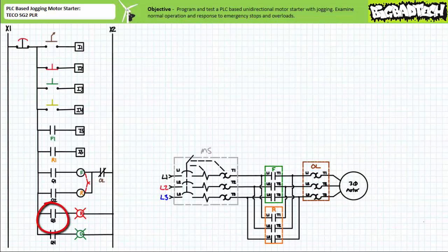Electromechanical relay output Q3 directs the operation of a red pilot lamp, and electromechanical relay output Q4 directs the operation of a green pilot lamp. Again, note the maintain contact normally closed e-stop serves as a hardwired bottleneck through which all field output devices immediately downstream of it must negotiate to be energized. Wired in this fashion, the hardwired e-stop directly upstream of all field output devices effectively severs all outgoing communication from the PLC without the necessity of resorting to any programmed instructions to do so.